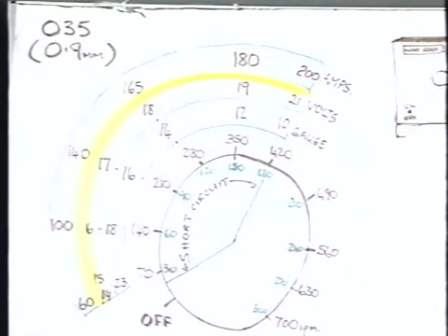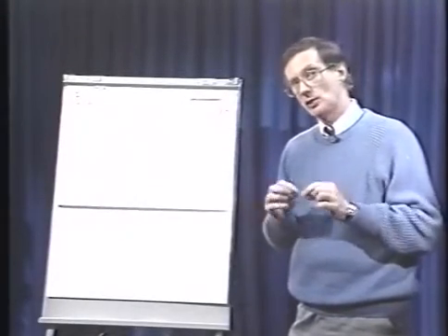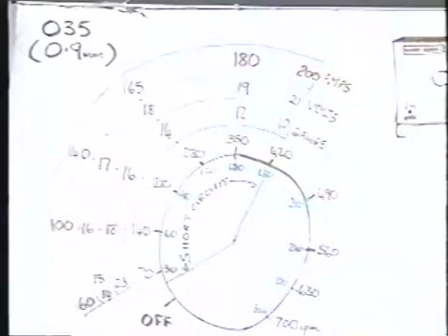A simple setting is as you turn each incremental control one turn, we go up 1 volt. The 9 o'clock position is 16 volts, the 10 o'clock position is 17 volts, the 11 o'clock position is 18 volts. And what about the thickness that we work with short circuit welding? What about the gauge thickness?